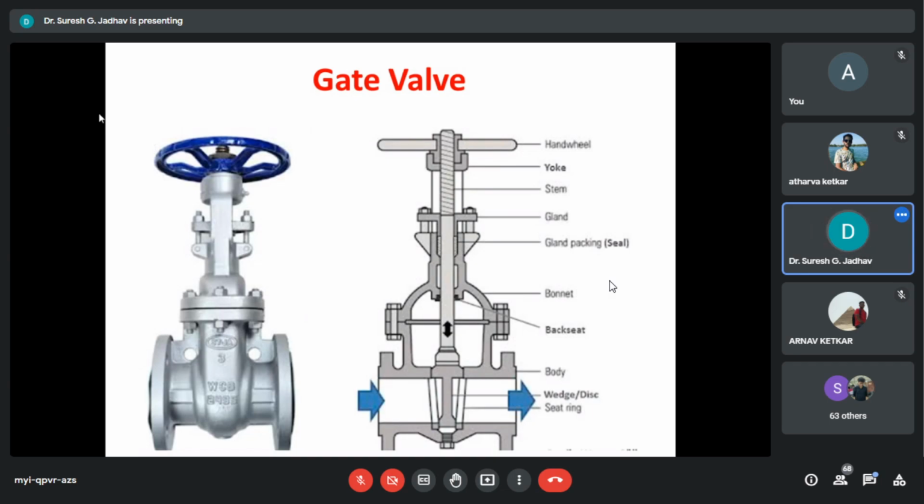This is used for the high temperature services. But this cannot satisfy the regulatory codes, meaning fugitive emission standards of greater than 500 ppm. Hence, the frequency of LDAR will result in excessive expenditure. So when we are using the gland flanges, packings and lanterns.